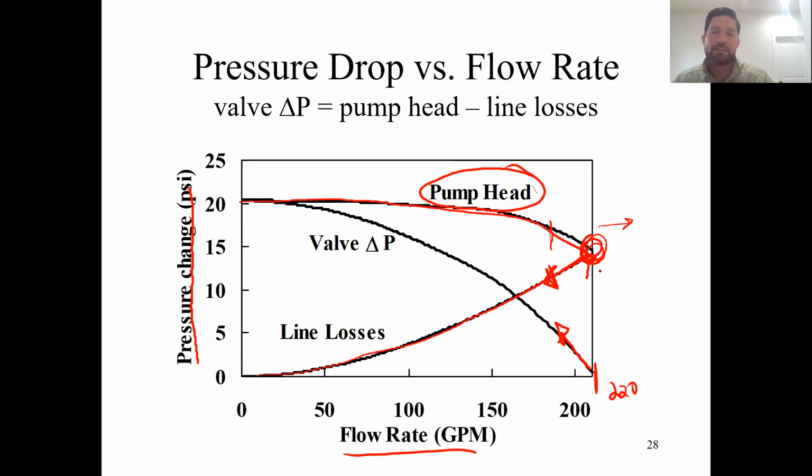Right, and so this question is a little bit ambiguous because you don't know what's the cause of the main line losses. If the main line losses were because the pipe was too small, or because you might have unnecessary valves or orifice plates in the system, you might go back and change some of those. But pumps are typically expensive. Repiping a whole plant could be expensive. So you can consider these two things and what's the most economical way to do it.